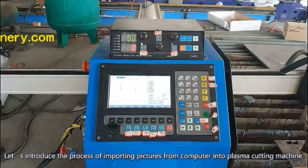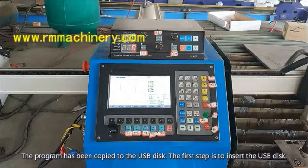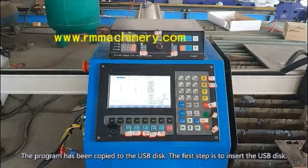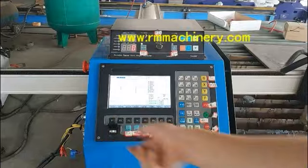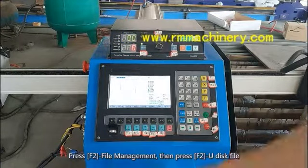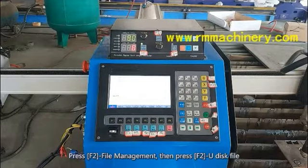Let's introduce the process of importing pictures from a computer into the plasma cutting machine. The program has been copied to the USB disk. The first step is to insert the USB disk. Press F2 File Management, then press F2 UDisk File.